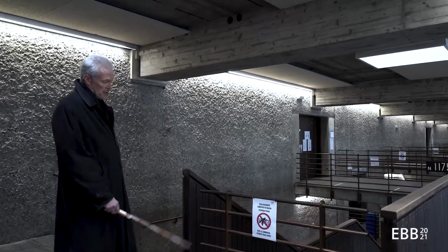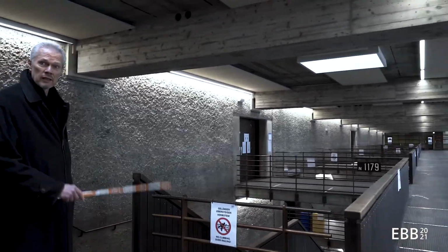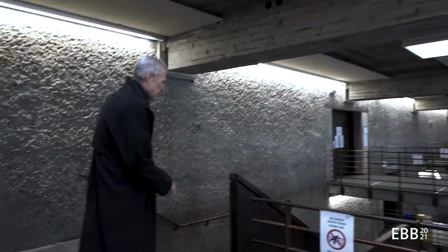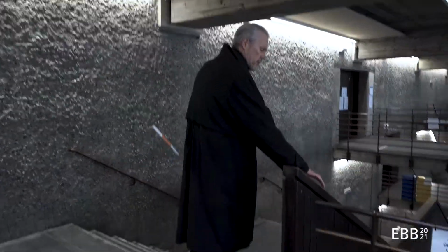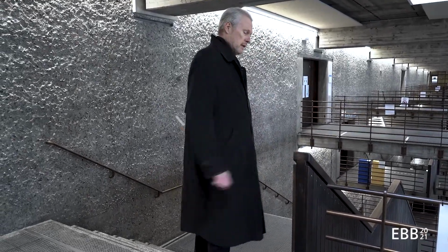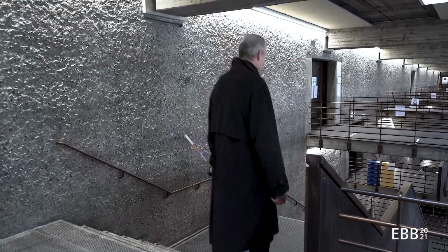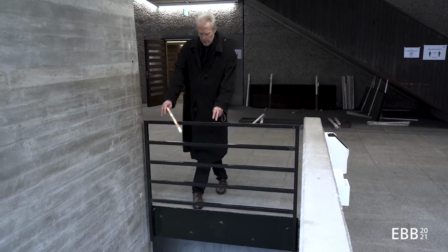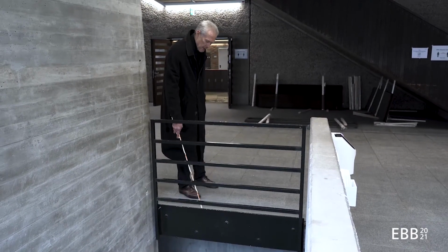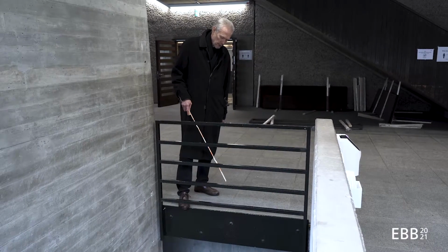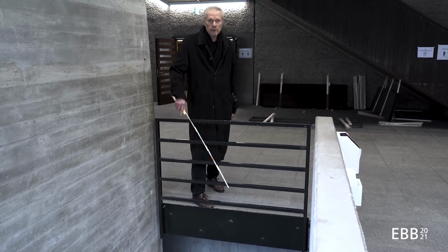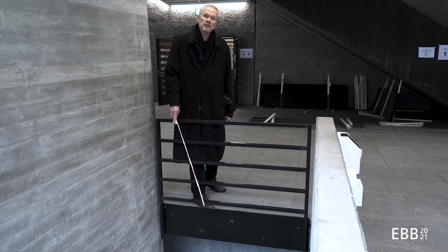So if you want to be sure that this doesn't happen, use vertical rods or a closed balustrade as this one here. Although this one doesn't have a nice handrail as this one, it's fairly safe though. So the railing is not very safe because I could climb up on it. And then what's nice is to have here the little board which prevents things from falling down in the hole, and then they would fall on the head of people that are walking up the stair.